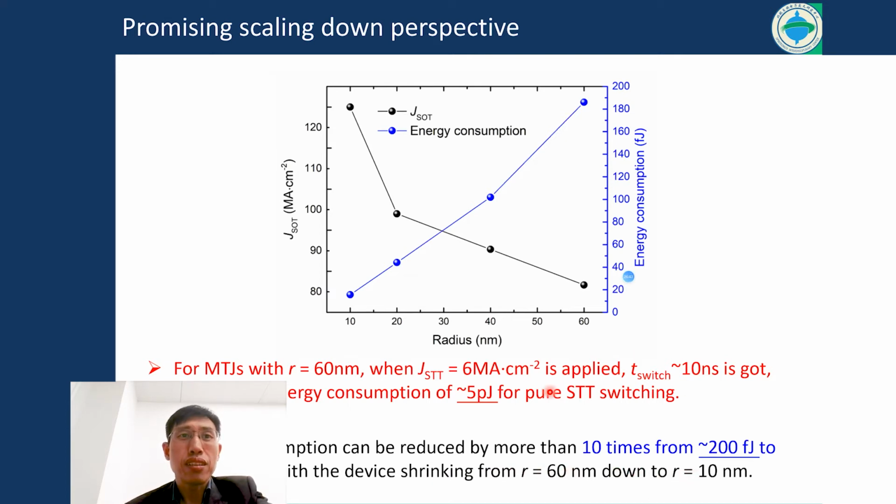This is the first step where we can use this interaction between two mechanisms to obtain ultra low power and improved lifetime. Here the energy per bit goes from 1 picojoule to 200 femtojoule.